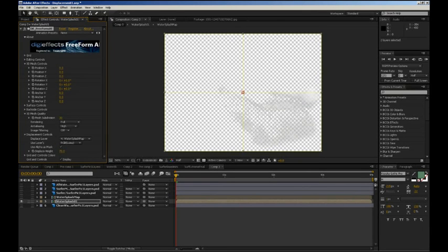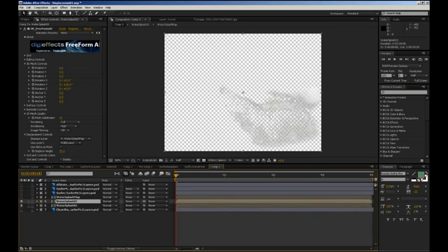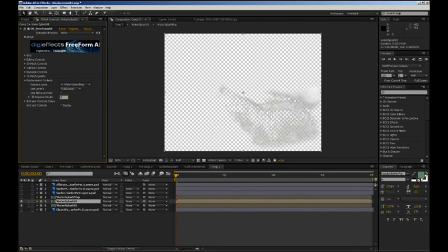And then I'm going to use the 3D mesh controls to change the position of this a bit. So I'm going to rotate this on the y-axis with 10 degrees. Now, just as Matthew suggested, I'm going to duplicate this layer and reuse it. I'm just going to change some of the settings for the displacement controls. I'm going to use 90 for the displacement height and then 20 for the mesh subdivision.